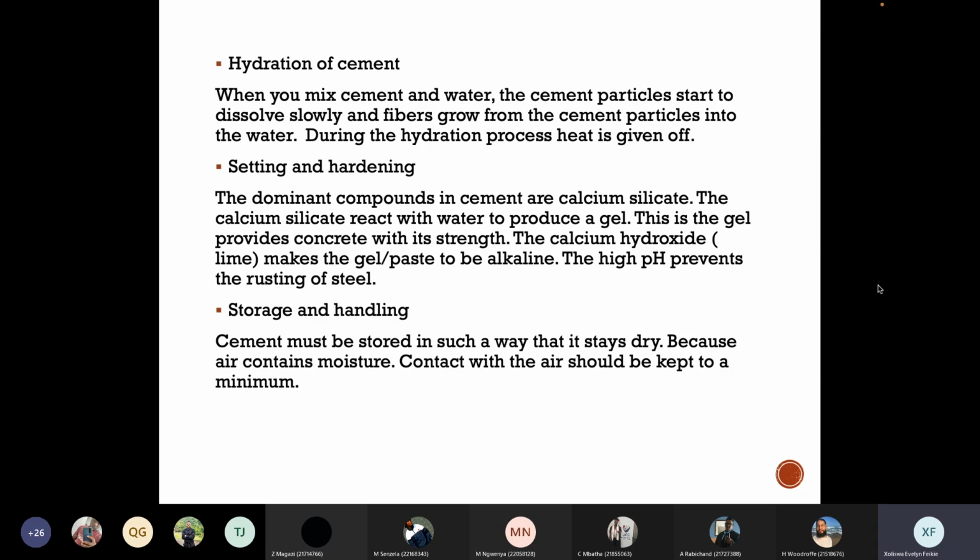If you've seen a construction site, sometimes you see that they wrap the columns with plastic. That's a way of curing the columns, but you can't wrap a slab with plastic. Then what do you do? Sometimes you spray it with water, or spray with water and cover it with something, if it happens that the slab we're talking about is exposed to the sun or whatever.